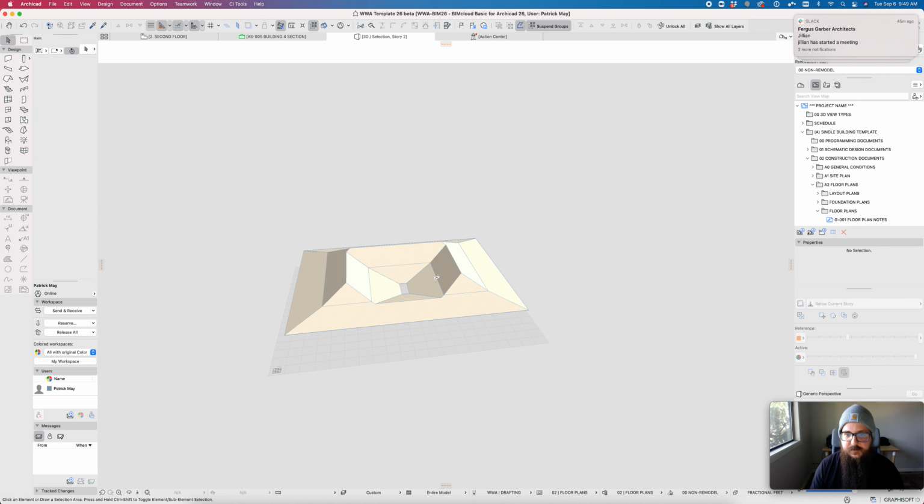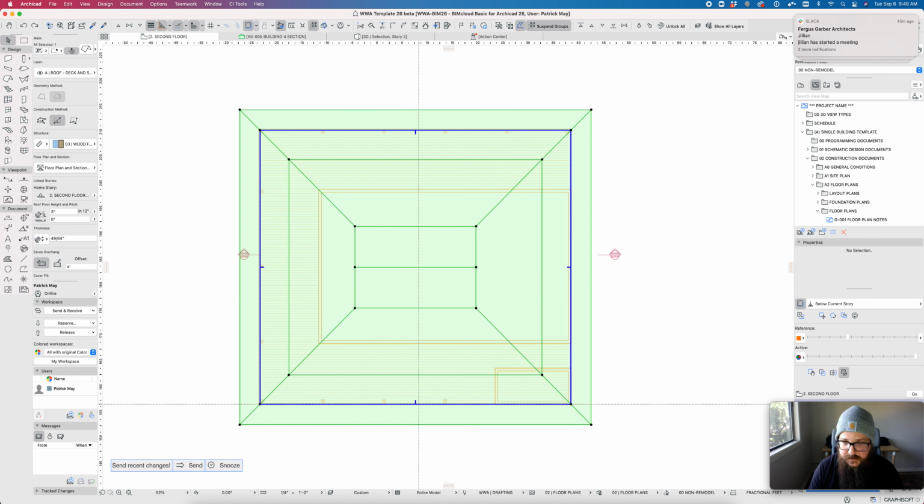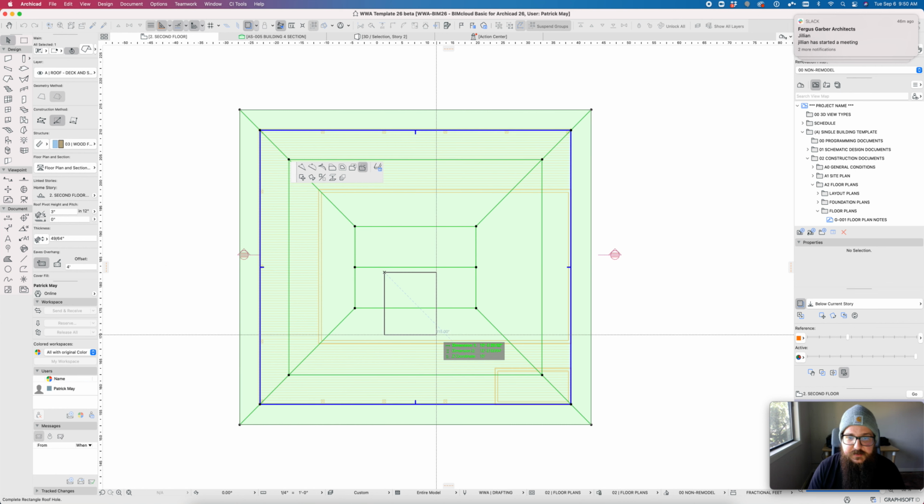That may be useful in some cases, but in this case, we just want to punch a hole in the roof itself. So instead of clicking and activating the pet palette by the blue reference line here, I'm going to click on the edge of the roof itself. And here I can click and say that I've got a roof opening that is, let's say it's 12 feet by, that should be X 12 feet, Y negative 14 feet maybe.